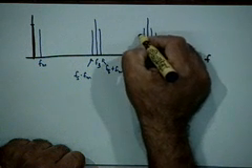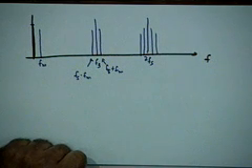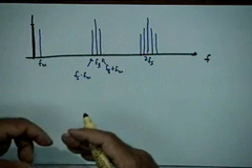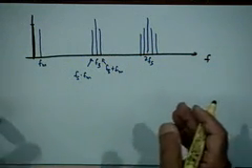But then there can be additional terms here, right? So just like we have many components in an FM signal, rather than only the two sidebands, we have many components here around fs, 2 fs, 3 fs, and so on and so forth, not just plus fm and minus fm, right?